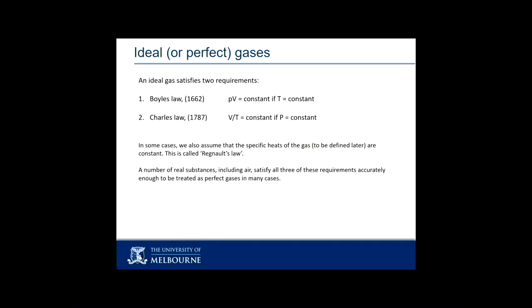Now, the neat thing is, almost everything that's a gas in our normal world is an ideal gas, which lets you make that assumption really quickly. If you're doing a problem, you're in charge of the analysis, and you realised first thing, I'm in charge of the system boundary, and I've drawn that, and I'm in charge of what's inside and what's outside. Second thing, I'm in charge of defining the working fluid, and I've done that, and I've said the working fluid is going to be air.